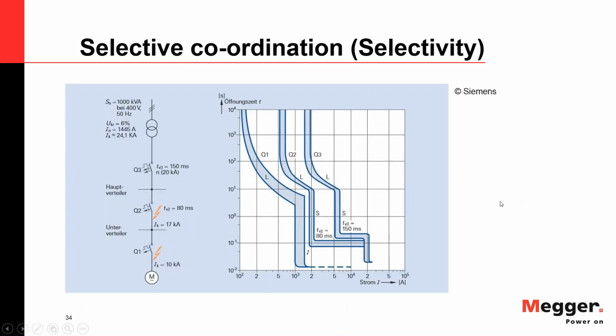Now just really quick, the whole thing, the whole testing and verifying the curve and that the breaker is still true to its intended curve is selectivity or selective coordination. That means you have different breakers at different levels in series, a main feeder, branches, and then a panel breaker, and depending on where the fault is, not all of these breakers should interrupt.